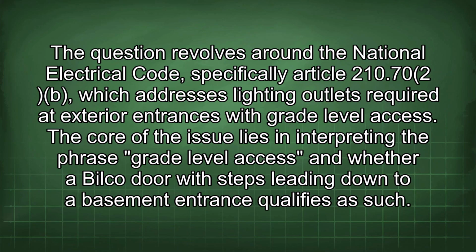The question revolves around the National Electrical Code, specifically Article 210.70, which addresses lighting outlets required at exterior entrances with grade-level access. The core of the issue lies in interpreting the phrase grade-level access and whether a Bilco door with steps leading down to a basement entrance qualifies as such.